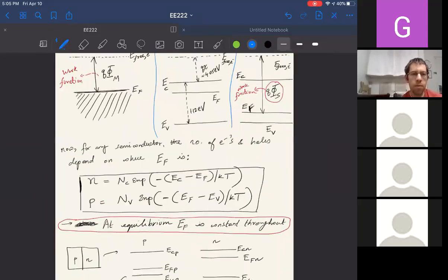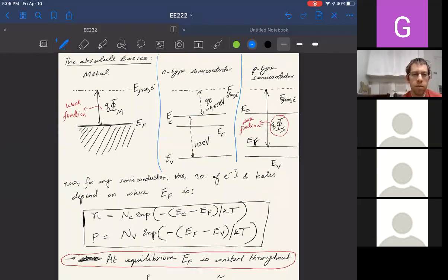So this is something that you guys would probably have seen before, but it's something you need to design the transistor. Just some basic things, like work function. Every metal is classified by something called the work function. The work function is the energy that is needed to remove an electron from the Fermi energy to E free, which is called the vacuum level. That's the energy level where the electron is freed from the solid, okay?